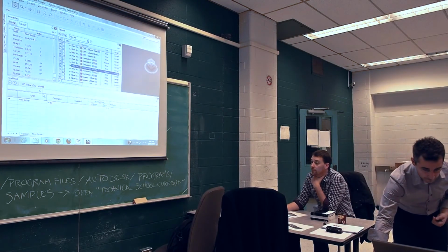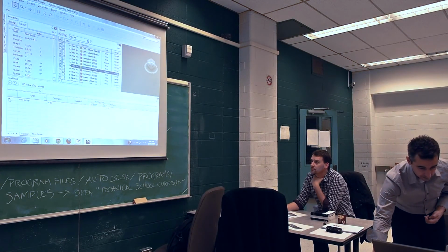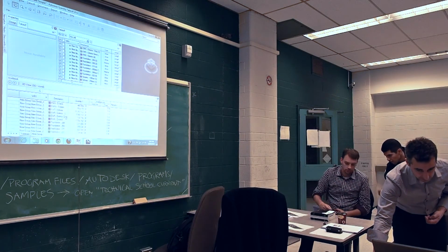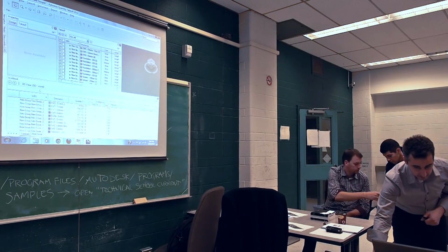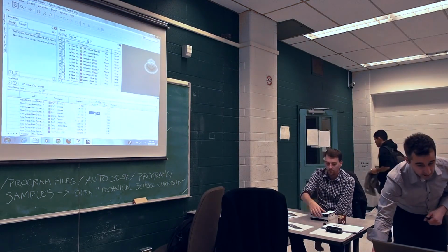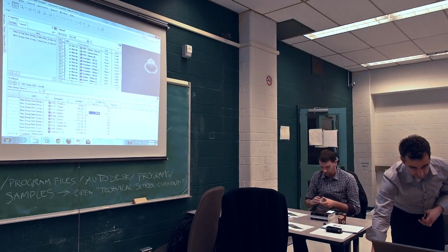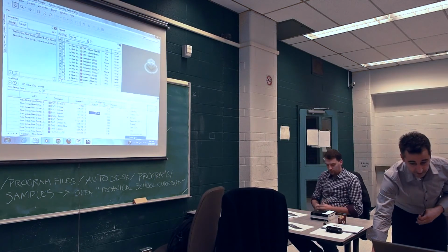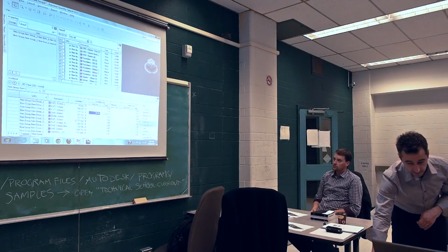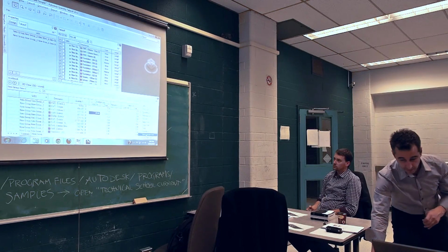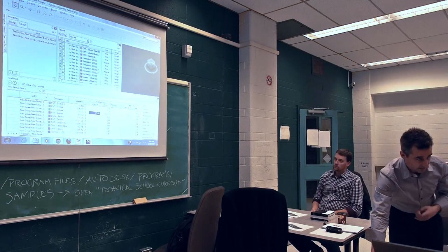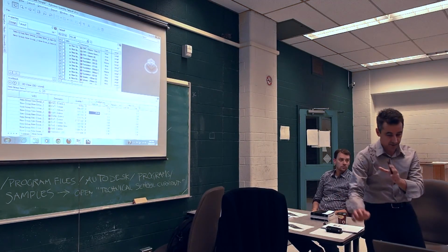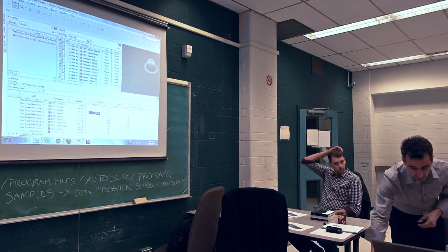And then this is my workbook. In my workbook, I can assign cost to this wall. Sure, I have material cost, and I can assign unit cost, meaning square foot cost. But I can also add labor cost, and I can also add subcontractor cost, and I can also add equipment cost if more than just the material is needed. So this is real, it's way closer to the actual estimating job.